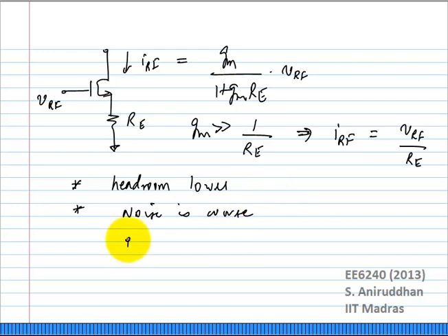Now I can use inductive degeneration, which will give you better headroom. There is zero DC headroom loss, and there is no noise also from the inductance.